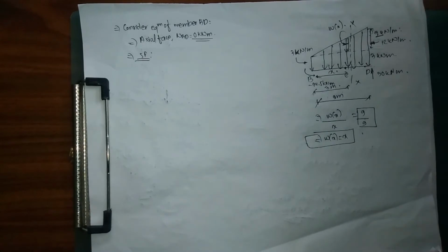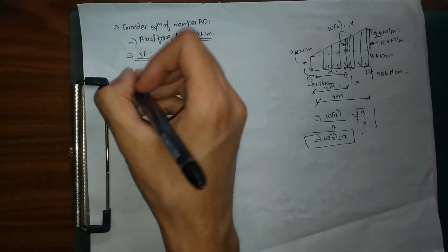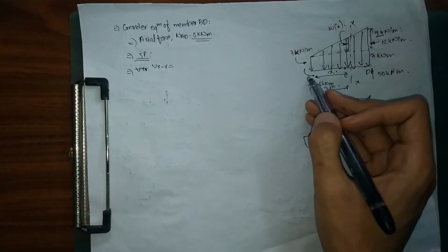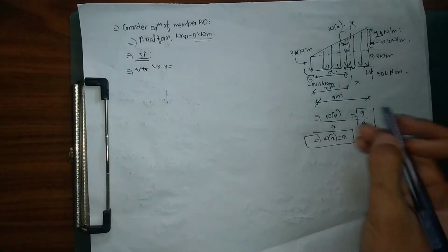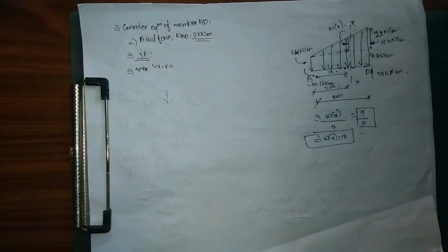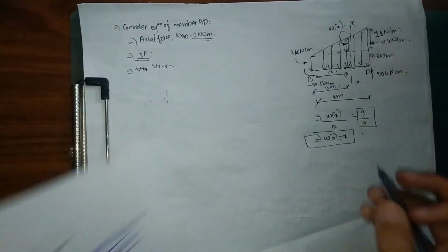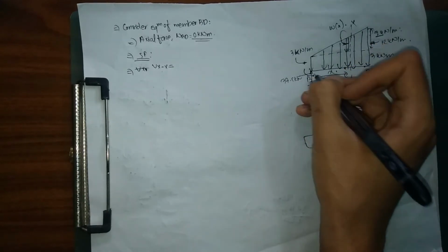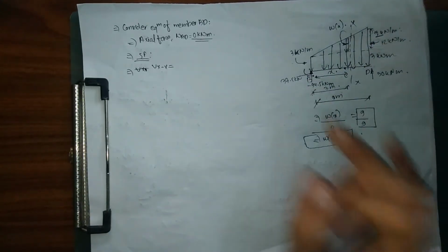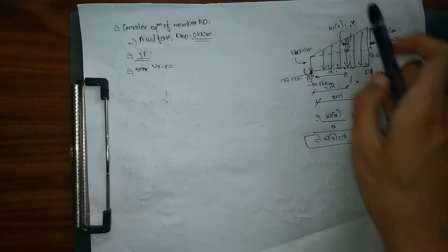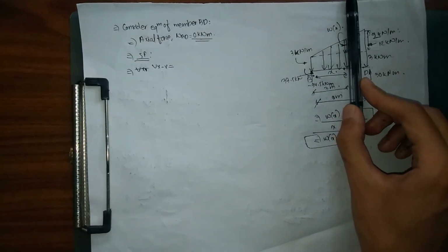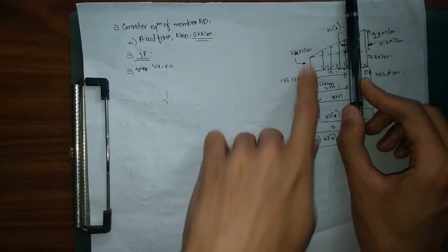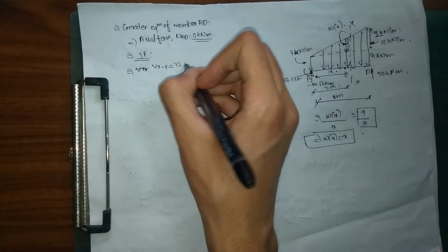So now we are going to solve for our shear force diagram. We are going to take shear force Vxx equals to, so right now we are moving from left to right, and as you can see here, we have missed one more force over here. At B we have 37.5 kilonewton acting upward. Now while we are moving from left to right, up to our section XX, first we have our 37.5 kilonewton acting upward, which means positive 37.5 minus.